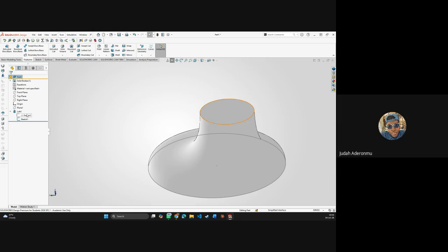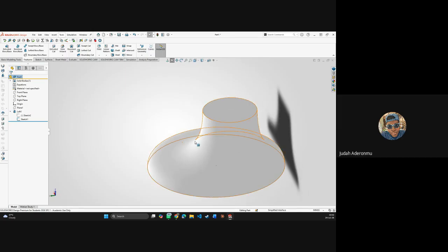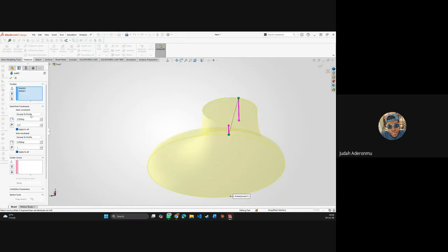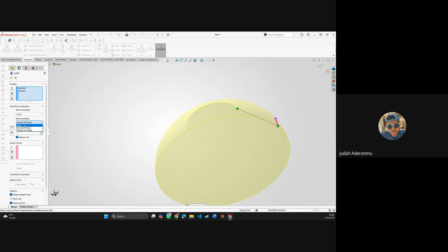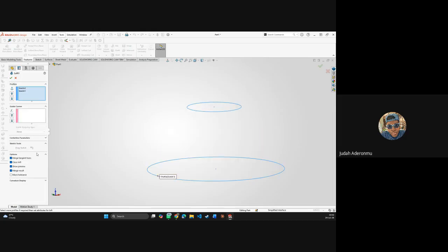Okay. So loft is when you have two sketches and want to just create something out of the two of them. And let's say let me just do none, start constraints here, none. If I choose none, then everything is just going to be straight. It's just going to project it straight to each other. Directly close lofts.